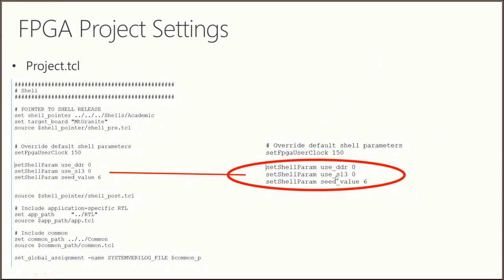The seed value is for the synthesis tool to generate random numbers. Many CAD optimization algorithms take random numbers as inputs, and it will directly affect optimization results. If you are slightly off by timing or having some strange timing issues, it's sometimes useful to test different seed values, but do not use seed of 0. This is a known bad value and will almost guarantee a timing failure.